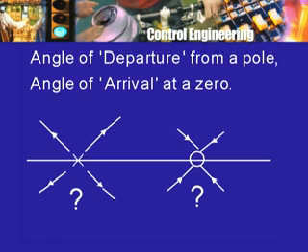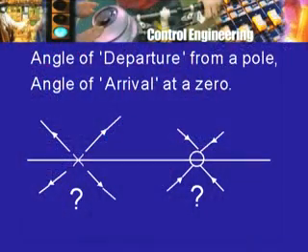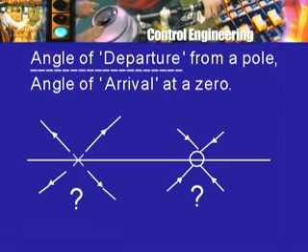Let us say here is a pole, so I know that a root locus branch will start from there, that is, for k very small there will be a root very close to this point. So there will be a root locus branch which starts at that point, but how does it proceed? Will it go like this? Will it go like this, like this, like this? For very small k, it can be approximated by the tangent to the root locus, so it can be thought of as a small straight line, but which direction? In which direction does the root locus branch take off? That direction is determined by the corresponding angle, which is called the angle of departure. Angle of departure from the poles of the transfer function, or the poles on the pole-zero diagram.